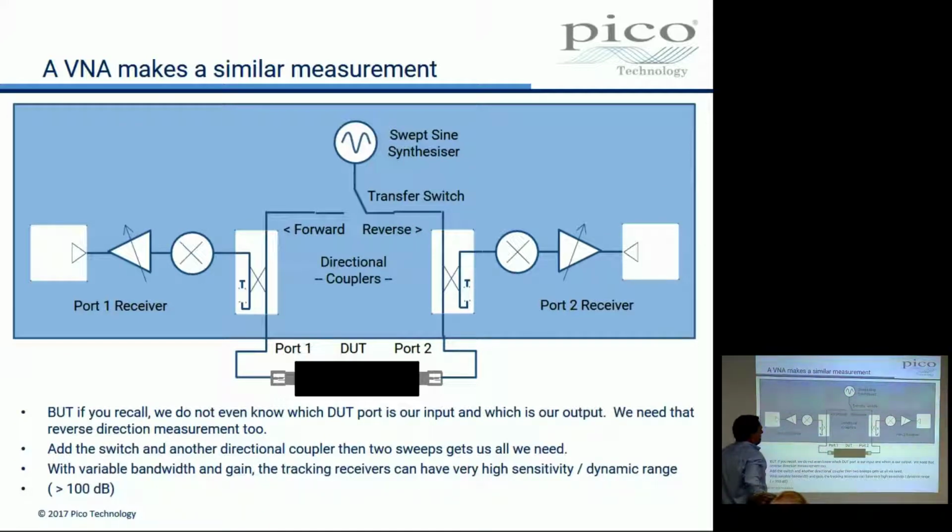What I'm now going to do, I'm going to put a forward and reverse switch in the VNA, because what we want to do is measure the signals the other way as well, isn't it? So we can throw the switch over and measure that path through that directional coupler. Oops, where did that come from? Oh, I had to add that, didn't I? I had to add that because when I want to go this way, I've got to go through a directional coupler in there and out of there, yeah?